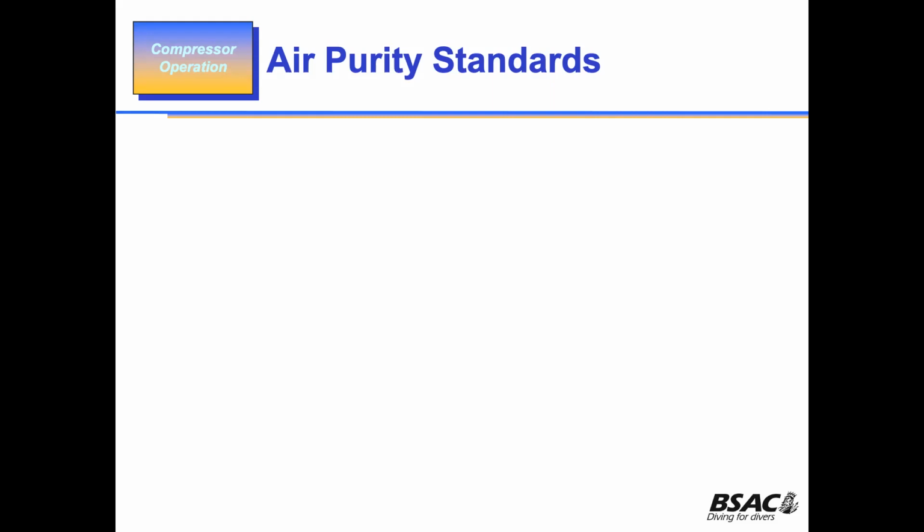Okay? Or you can take a sample of your air compressor and send it off to a lab, and the lab will do the air purity test for you. Then they'll send you back a certificate to say you have met the standard or you haven't. A lot of commercial companies send it away and have a test done that way because it saves time and it also saves money.